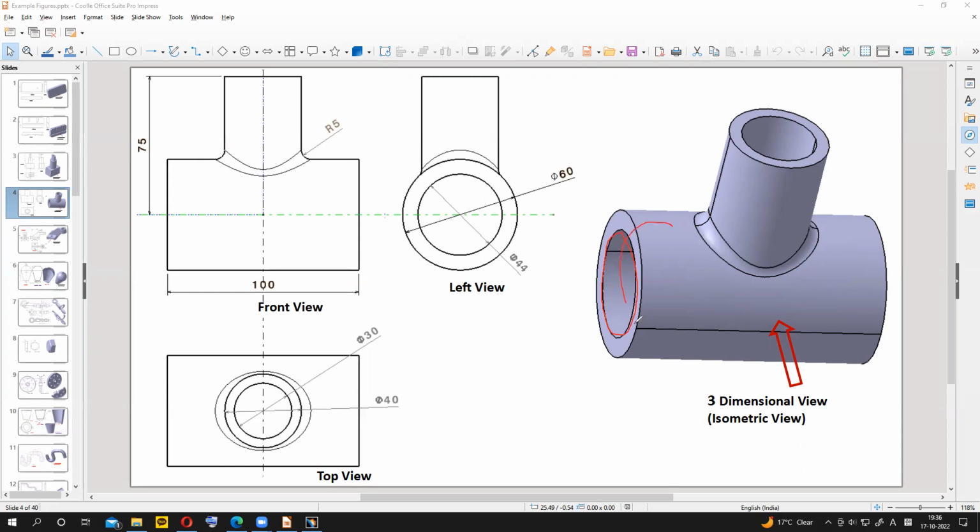For the top cylindrical part, we have to use the top view. First make a circle and pad, and later make a hole or pocket: make the circle and pocket up to here. So inside of this, there is no material, but not up to the bottom, only up to the next section. Let's get started making this one.